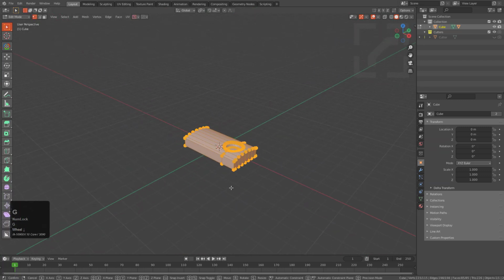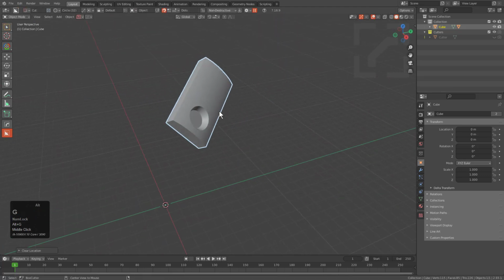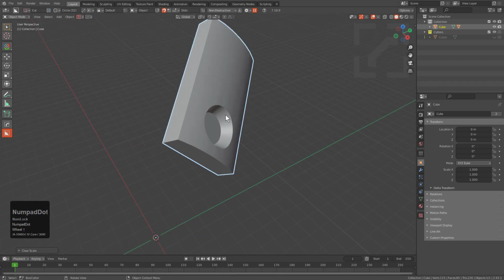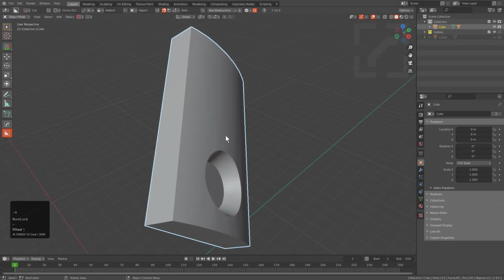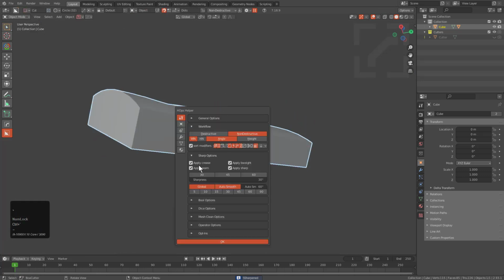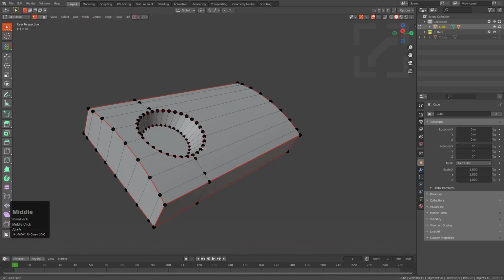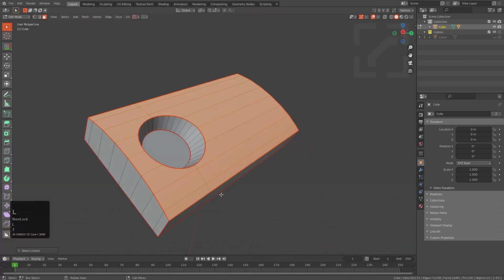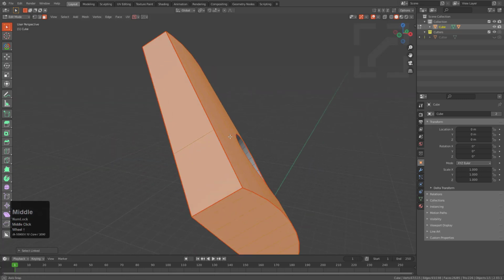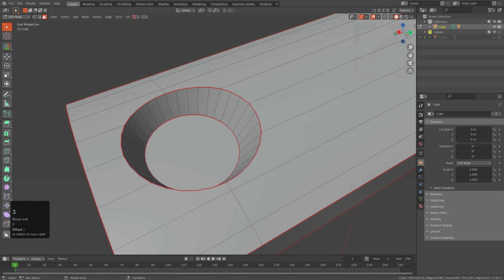But the main thing we want to do here is take the object in edit mode and rotate it, so that way if we press Alt G, Alt R, Alt S to rotate things, we don't actually have that level of control back. So the first thing we'll do is sharpen it, because our Control tilde settings are set to mark seams. So that means that all of our boundaries are marked. And if we go in face mode, we can press L and we can select things that are isolated by boundary selections if we use UV seams.